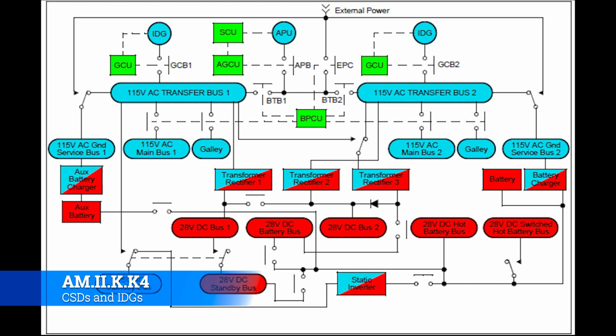You have your static inverter, and then you have your AC standby bus. So if the AC standby gets kicked on, it can go into the static inverter, and that will invert electricity and then supply it to the DC system, charge the battery, all that good stuff. So that's kind of the 737 Max's hierarchy of how power flows around.